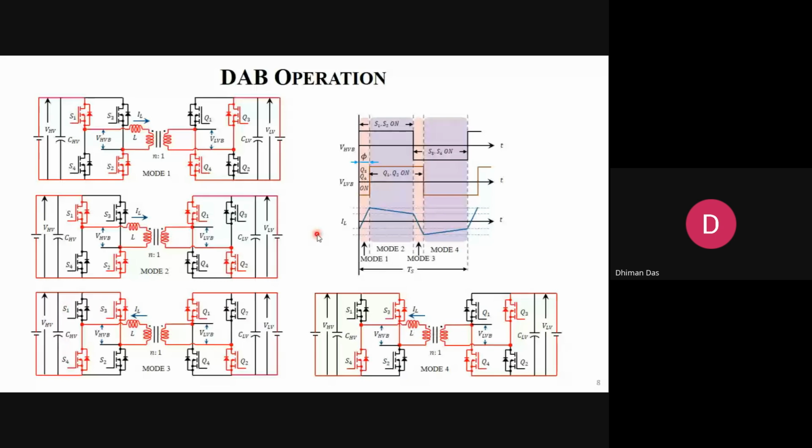So a huge amount of flux will radiate from your converter, and when this flux radiates, it is called radiated EMI. This radiated flux can interact with any kind of conductor nearby and produce eddy current, and that eddy current creates noise, and your controller can malfunction.